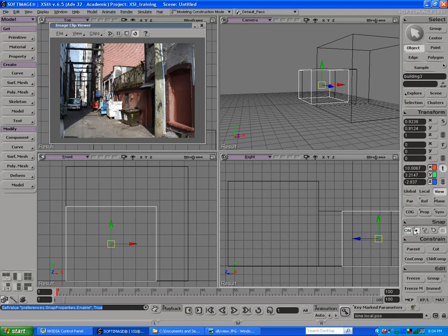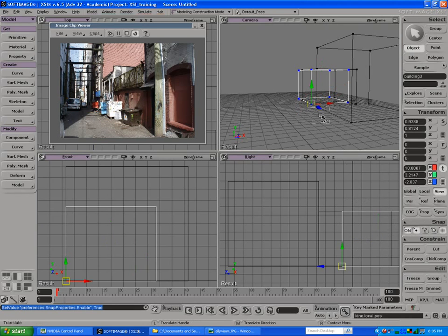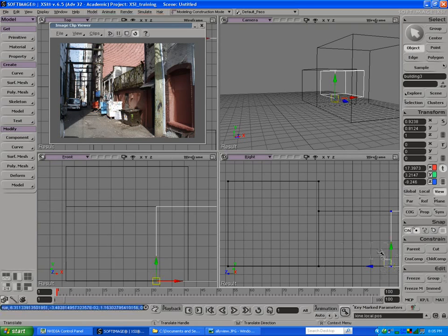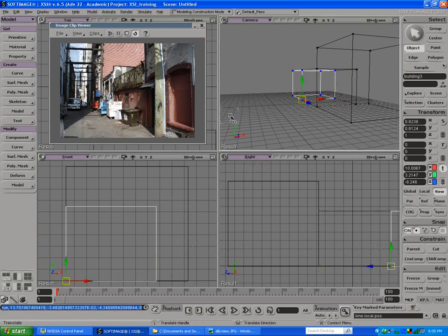It's already set to point snap. And you can actually see, with the right mouse button, what snapping options you have. Again, we use the temporary pivot, so we'll just go Alt and drag. Alt and click to drag on that pivot, and then again we'll just drag it till it snaps. It snaps in the wrong place in that case. We're just going to drag it here, get it snapped in this window.